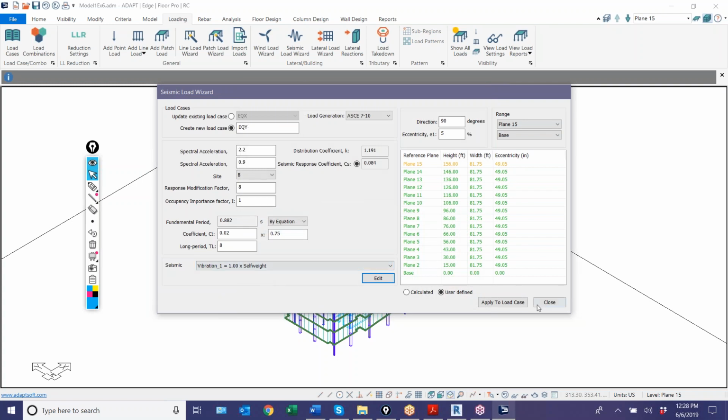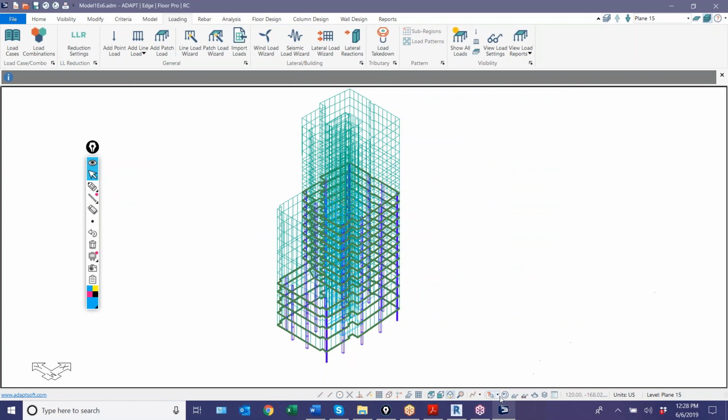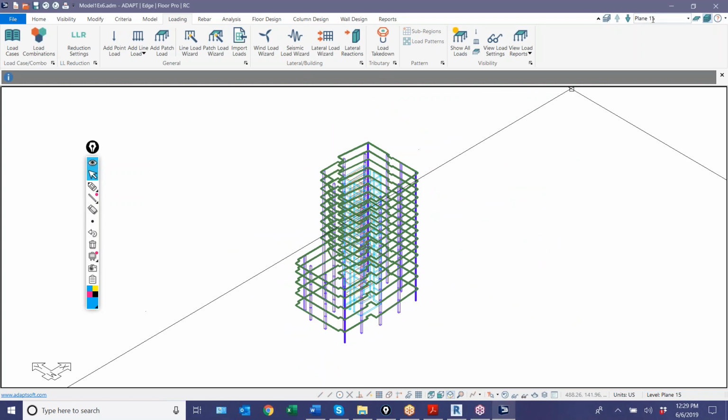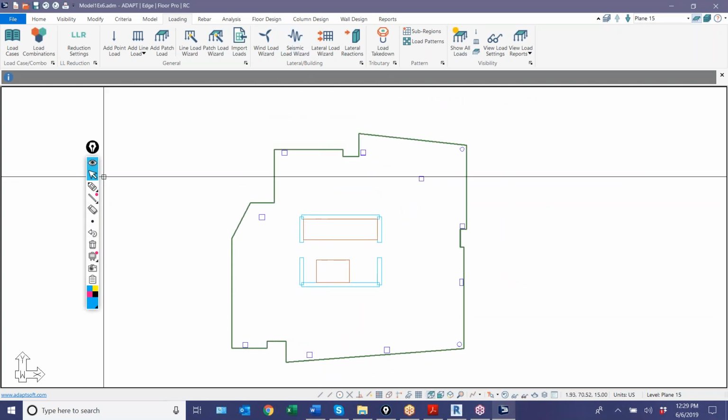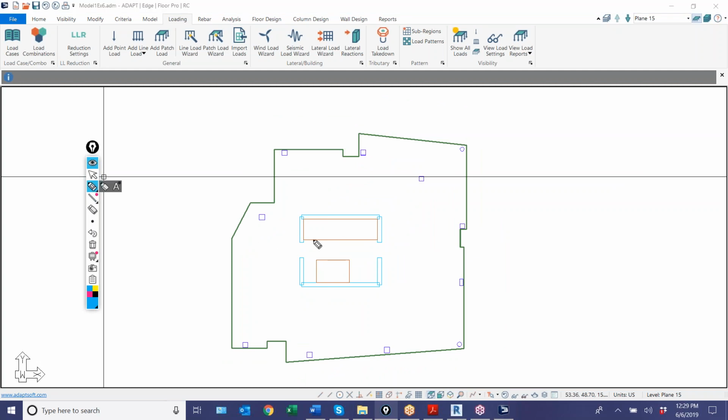Once we set up this data, let's assume, at level 15 again, I'll use this as my example, that based on that data the shear in this level is 100 kips. And rather than assuming a rigid diaphragm, saying the center of mass is right here, calculating the center of rigidity, and then applying the force in that fashion, our diaphragms are not assumed to be rigid or flexible. They're, in essence, semi-rigid. They're a shell element. They have both in-plane stiffness and out-of-plane stiffness.